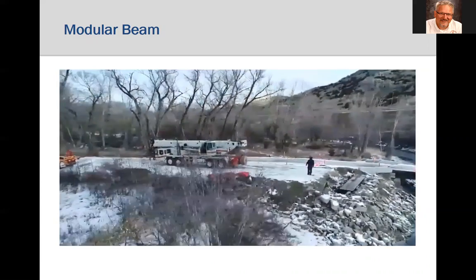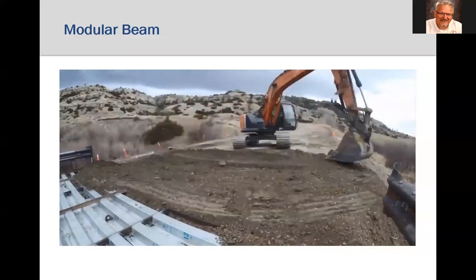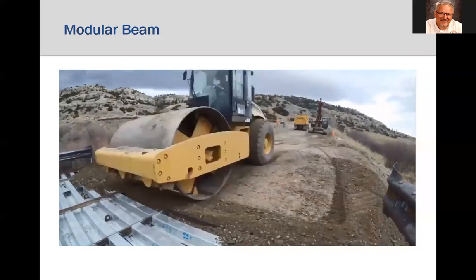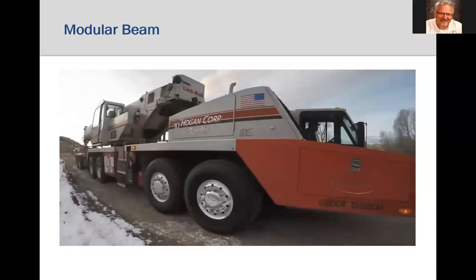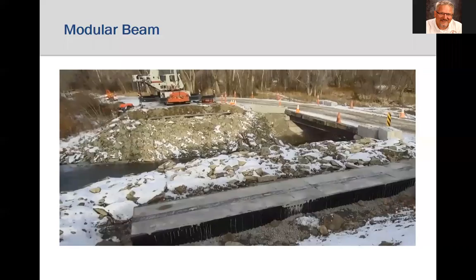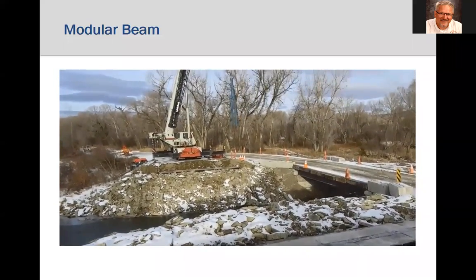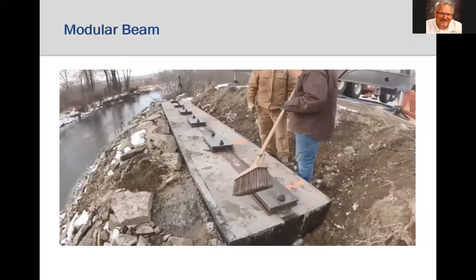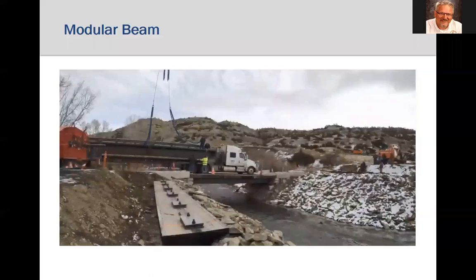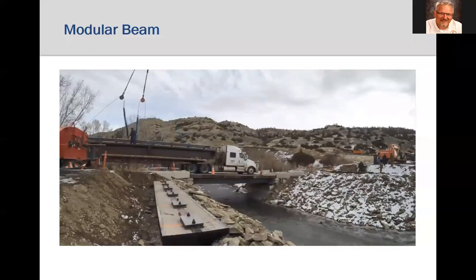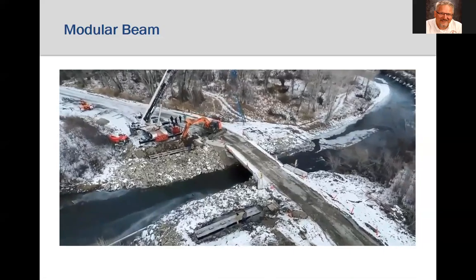Swamp Creek Bridge for Sweetgrass County. It's a 24-foot wide by 65-foot span, pre-engineered modular steel bridge designed and fabricated by True North Steel. This particular job utilized the Supersill abutment system, which is a steel box form that consists of structural elements, and once set and installed, is filled with concrete. The supersill abutment is typically utilized in situations where the soils are conducive for a perch style abutment or a spread footing.